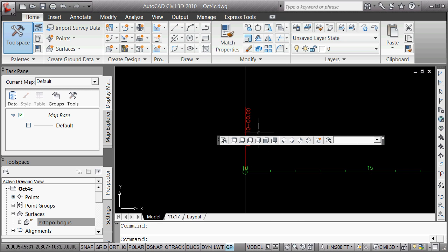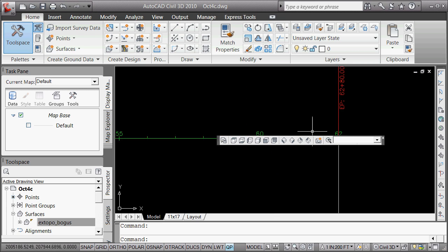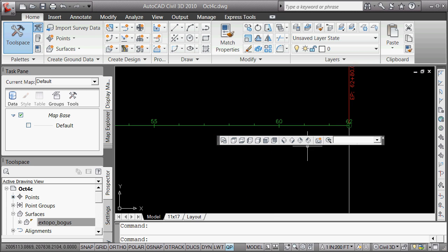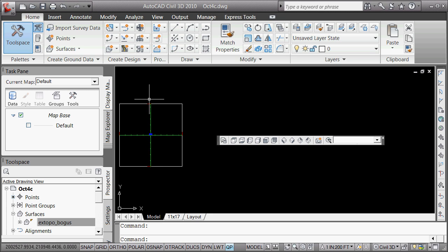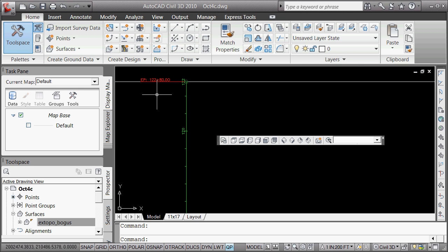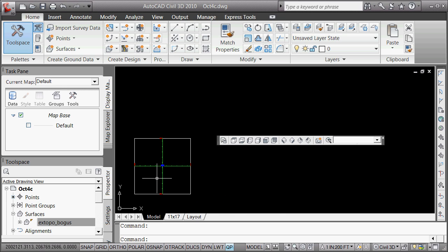stations, and if it's a mile across, that should be easy. Should be 6280 and 70, and then up again to 122.80. Write these things down. One I really want to know then is the center line, which is at 36. The intersection station equation is 36 plus 40 equals 96 plus 40.